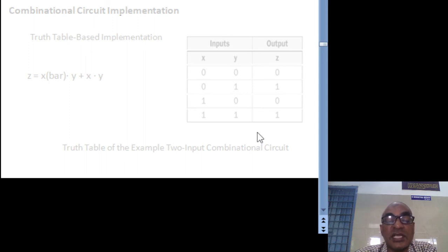The CLB is the unit to realize the function, but the realization happens through LUTs, the lookup tables. The lookup table consists of RAM-type memory, multiplexers, etc. So that is the lookup table and CLB.